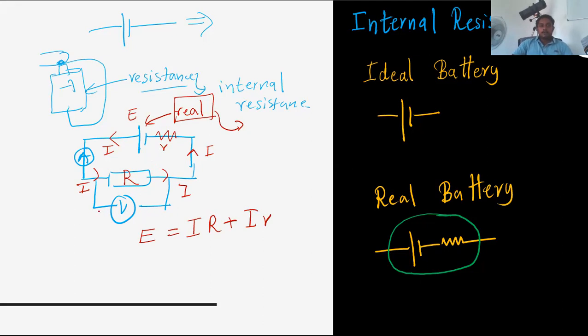Consider the voltmeter reading is V. The voltmeter reading is giving us capital IR only, because we are measuring the potential difference across these two points. Now subjecting IR, I'm getting E minus Ir. Finally V is equal to E minus Ir for a battery.